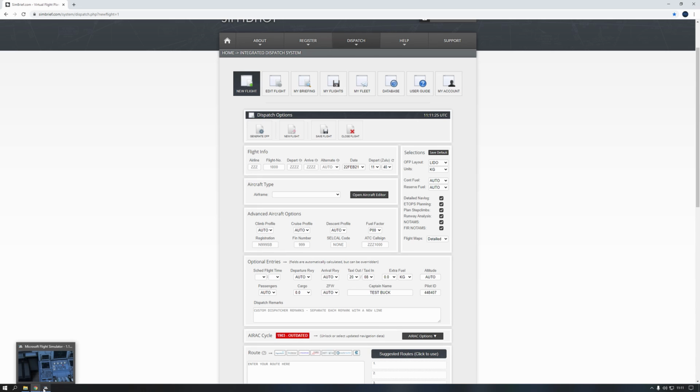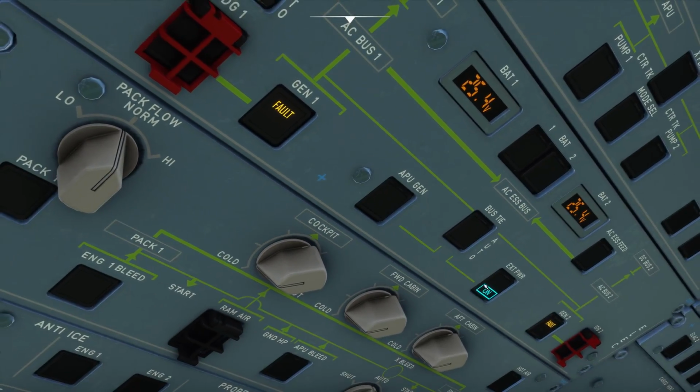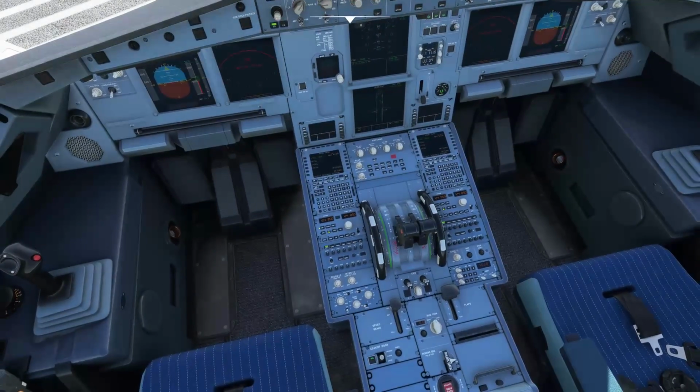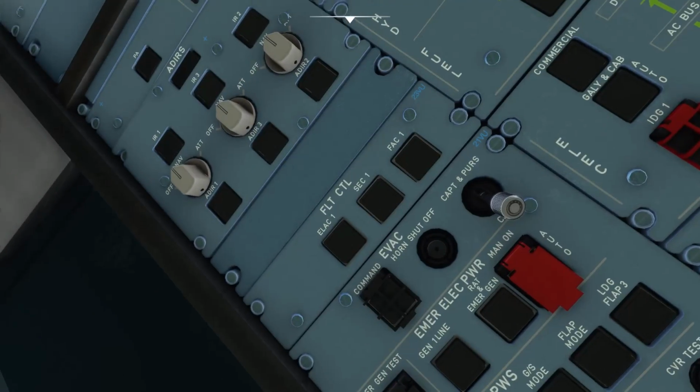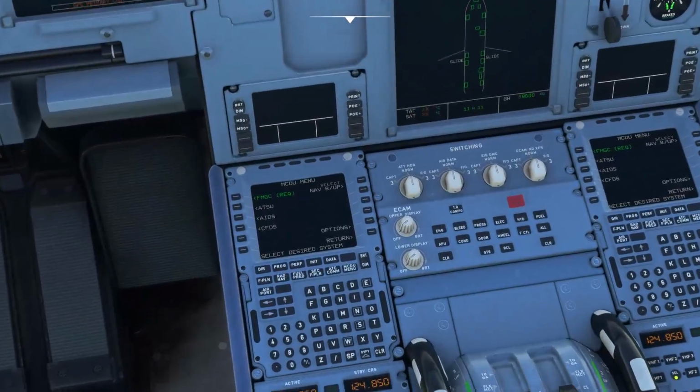We're now going to go back to Flight Sim. In here we're going to go to Options. This is the MCDU menu that comes up once the aircraft has been started. Again, we're at the point where we've got external power on and nothing more. And again, if you have watched the tutorial, you'll know you need these set to nav, otherwise you won't see anything to do with the flight plan.